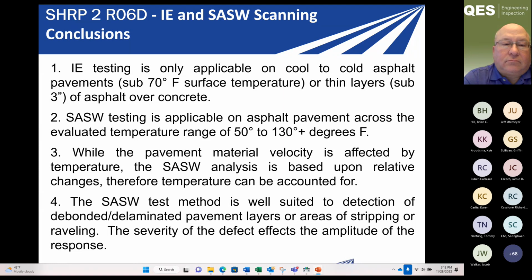However, when you get up to the warmer asphalt layers, the IE test was no longer working well. And the reason for that is the asphalt gets soft enough that the impact just can't generate those really high frequencies that are going to resonate that pavement like they would a concrete. So the IE test has no problem on concrete at a whole variety of temperatures because the concrete's so hard. But once the asphalt warms up and softens up, it's just really difficult for us to generate those frequencies up there, the 5, 10, 15,000 hertz.